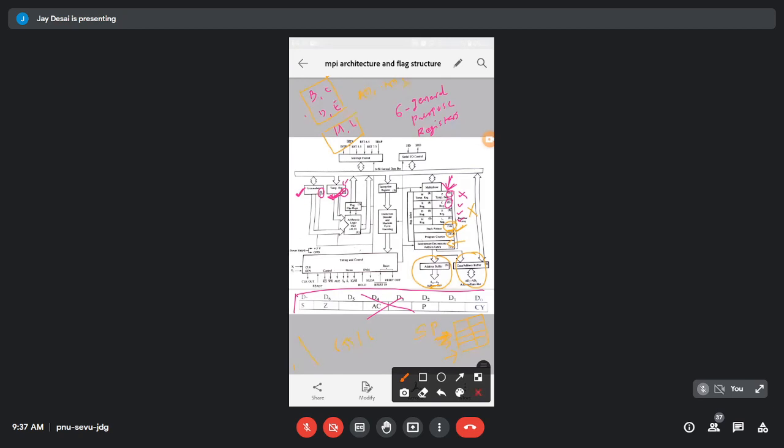A means address, D means data. ભૂલી ગયા કે યાદ છે? Yes, sir. હા. So AD0 to AD7 is known as the multiplex pins, or you can say that multiplex bus. It contains the lower order address bus as well as the data bus.